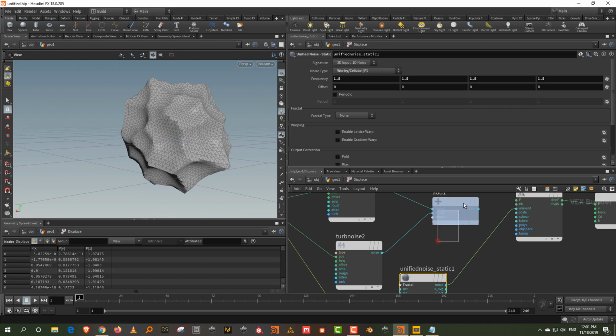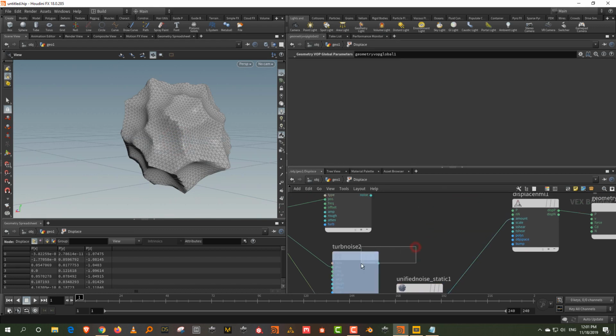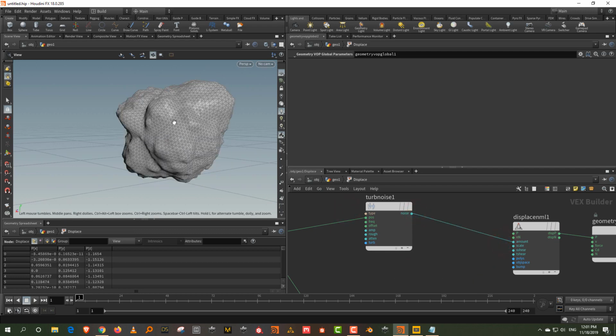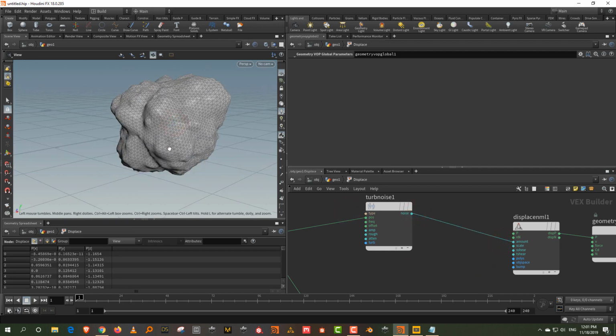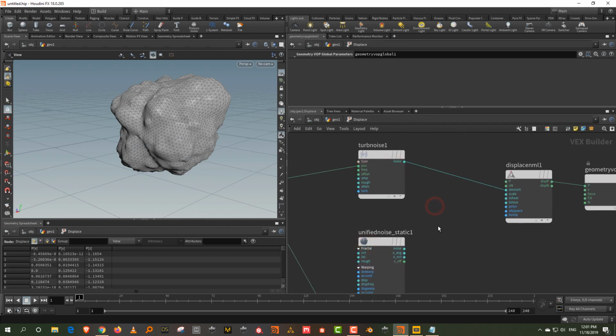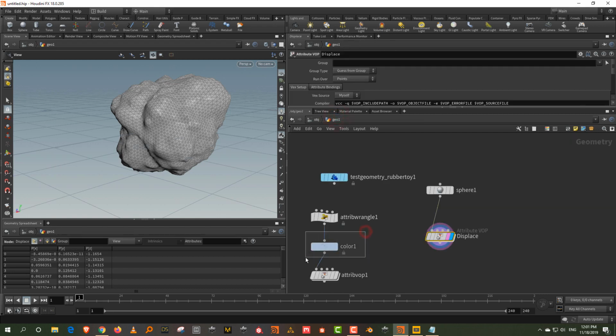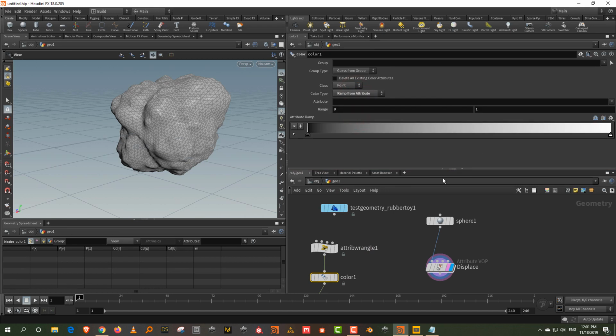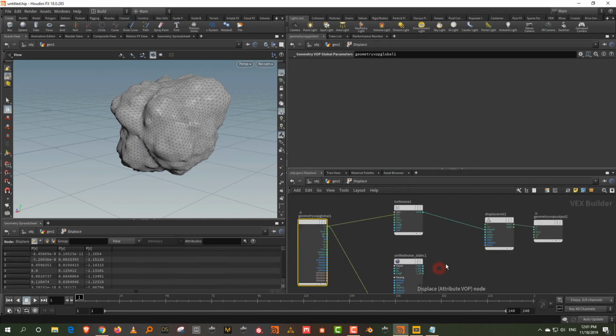Okay, and let's say what I want is to mix this together using a gradient. So I want to do a y-axis gradient and then mix it with that. Here is where things become a little more interesting, which is that you can create parameters. We saw how to create a parameter, but you can also create ramps. Essentially, when we take the color node, you have this option called ramp, which generates a ramp. We can do the same thing within a VOP.